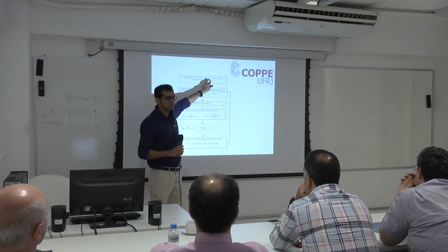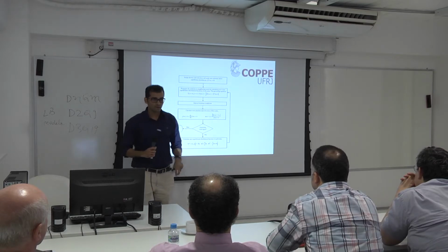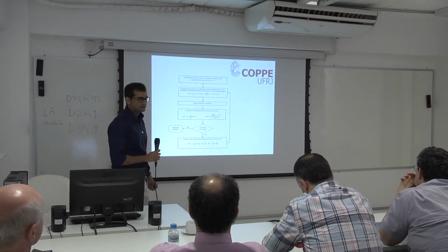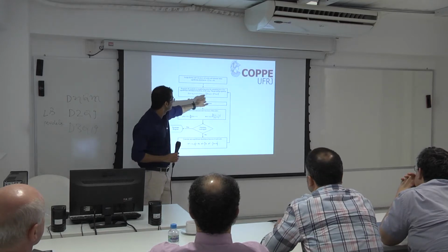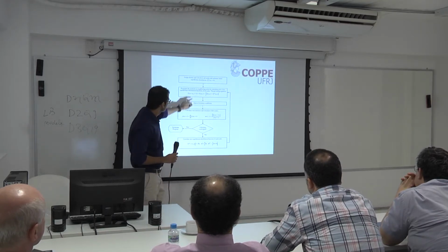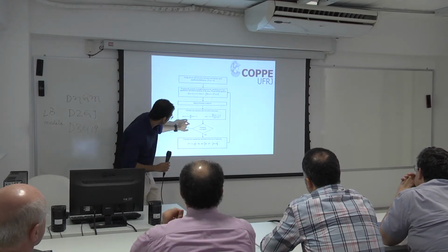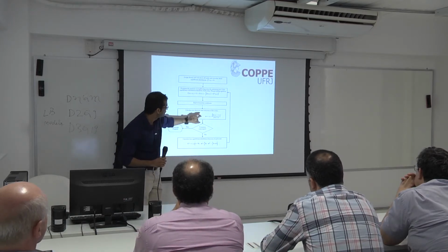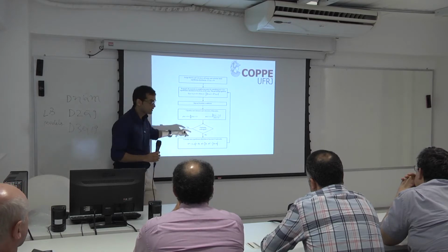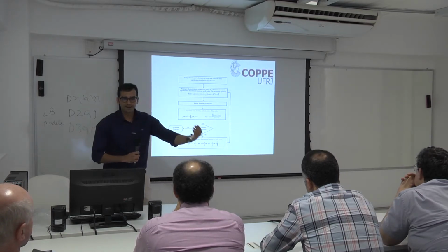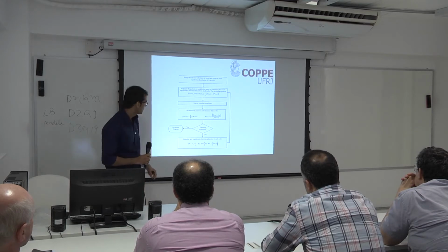Assign density and velocity, like we already have talked about. We have the propagation equation. We impose the boundary conditions. We come back to the density and velocity again. New density and velocity for what? For the neighbors, for the next lattice points.